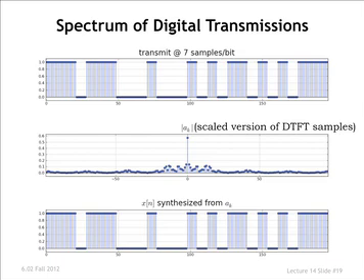Okay, so this might be a typical finite length sequence. In this particular case, we had chosen 7 samples per bit. That's why the shortest interval you see has 7 non-zero bits there. Here's the spectral content of the signal.